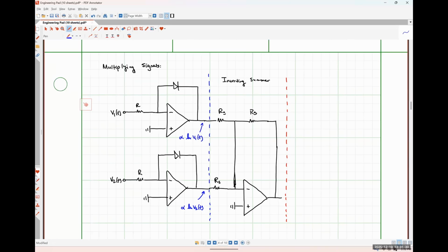At the output of the summing amplifier, at this point, we have the natural log of V1 plus the natural log of V2, which is the same thing as the natural log of V1 times V2. And so now we need to do the anti-natural log so that our output signal looks just like the product. Okay. So this is where the anti-logarithmic amplifier is going to come in.